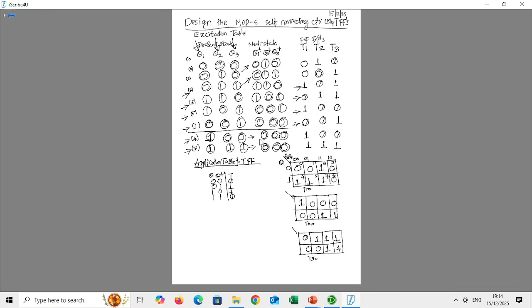It's very important: if you fill the don't care, the circuit will be simplified, but there is a chance of getting into invalid operation. So it's better to always make every state predictable. That means when it enters any invalid state, predictable behavior should happen.